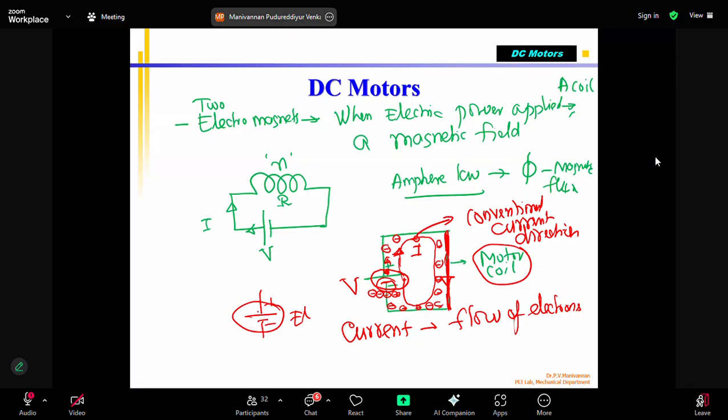There are 2 metal electrodes. In a lead acid battery, one is called PbO2, lead oxide, the other pure lead Pb. One is the positive, the other one is the negative terminal. And if you don't fill the electrolyte, generally diluted sulfuric acid in lead acid, nothing happens.